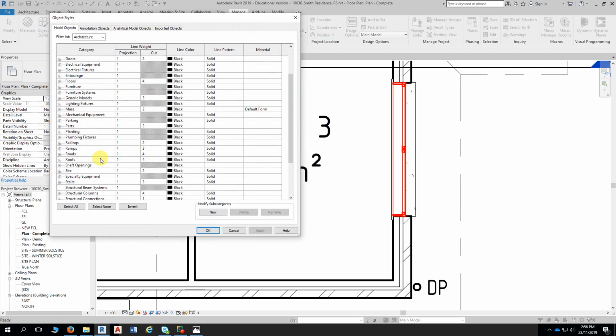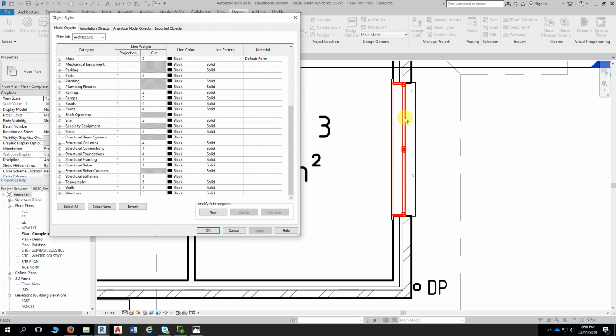So again, if I wanted to back off the line thicknesses in here, and again, just bearing in mind that the display line thicknesses here are not necessarily how it's going to print. Okay, so there might again be a slight variation when it does actually go to printer or print to PDF. So it's just a rough indication of what the thicknesses are relative to one another.